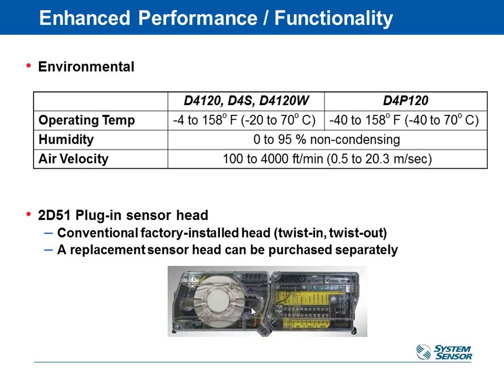These guys can be installed pretty much in any duct system that you have. In terms of operating conditions for HVAC, it goes all the way down from -4 up to 158 degrees, which is pretty much our normal range. 0 to 95% humidity. That's all normal stuff for both the indoor and outdoor unit. The outdoor unit can also go down to -40 instead of -4, so that guy can have an even better operating range. The really cool thing about these guys is the air velocity range.